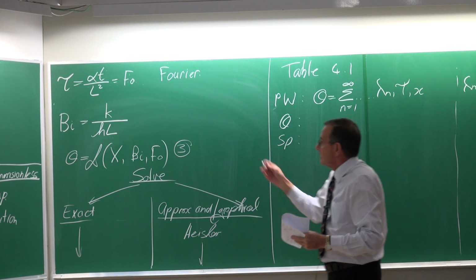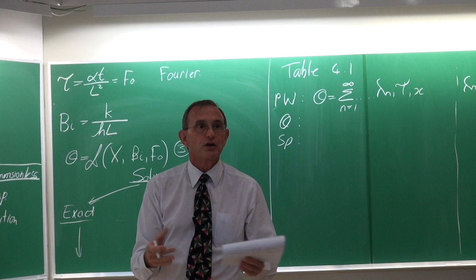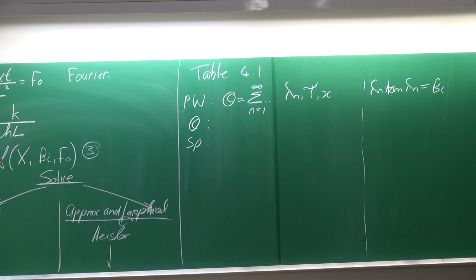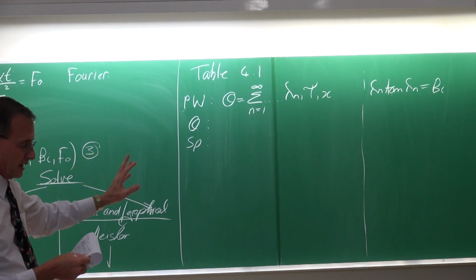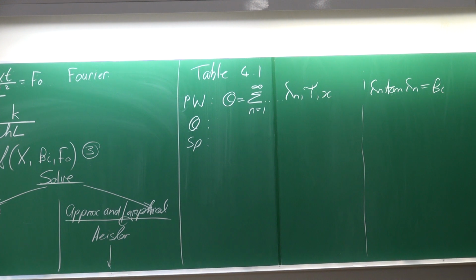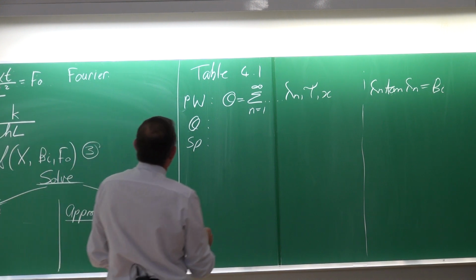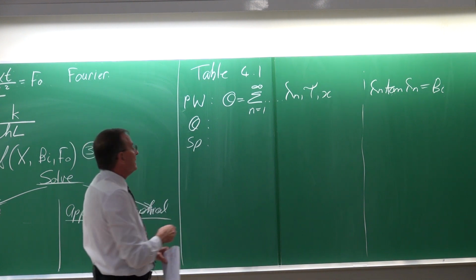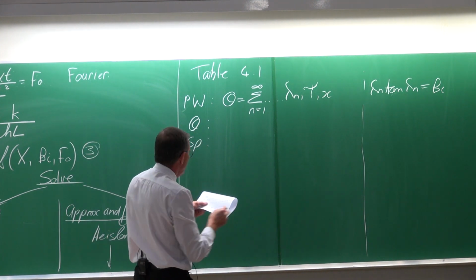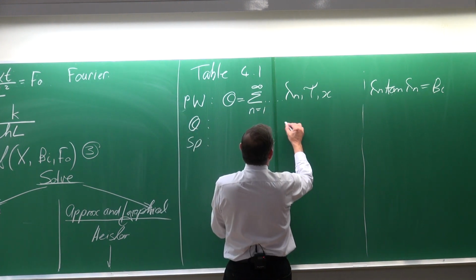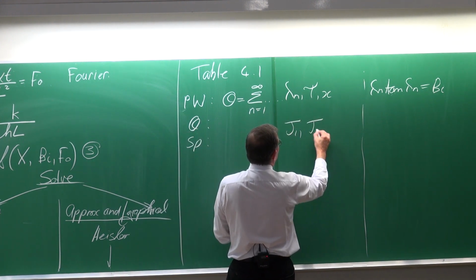How did they get there? They made use of the method of separation of variables. And together with that, they identified the characteristic equation, the eigenfunctions, the eigenvalues, etc. Now the plane wall is the simplest of all of them. It is then followed by the solution for the non-dimensionalized temperature, and then you will see also those things, but now a J1 and a J0 jump out.